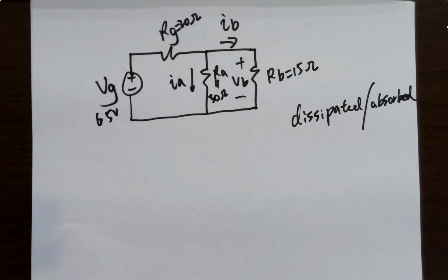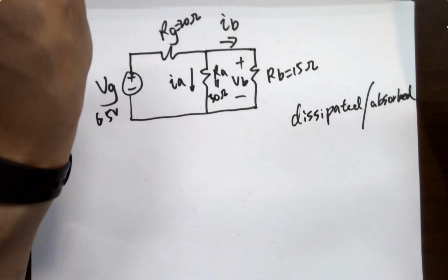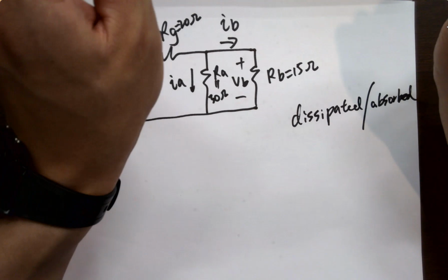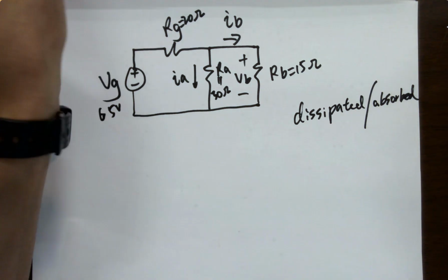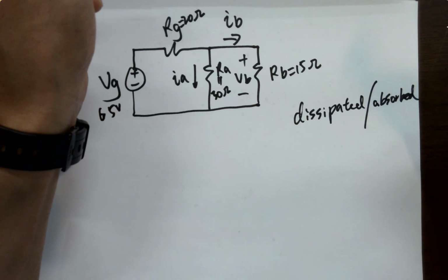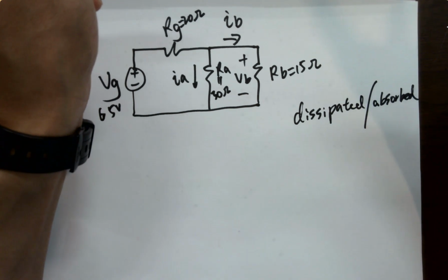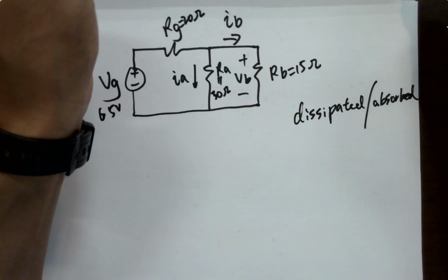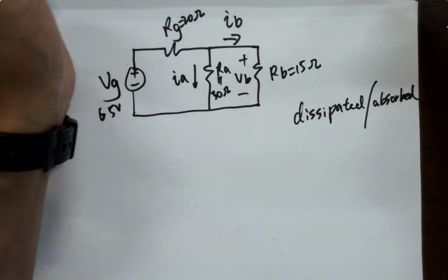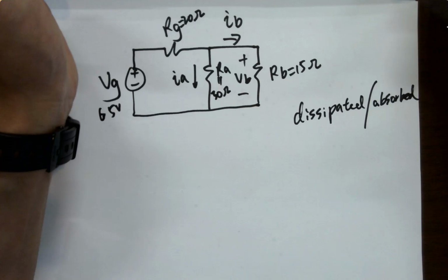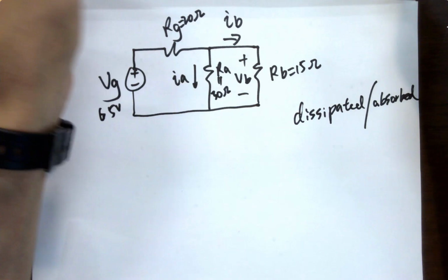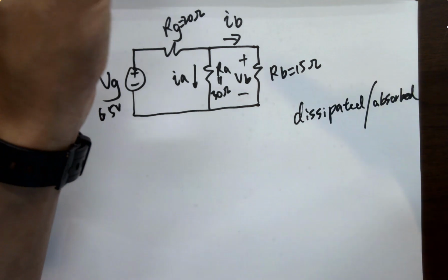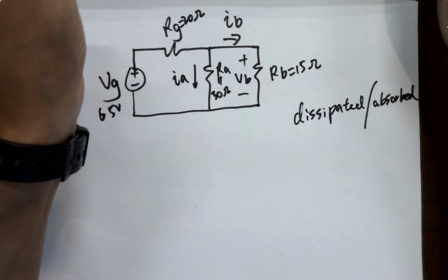So I discovered that the freezer has a heater inside. Can't believe that. The heater is a low resistance resistor, usually 20 ohms. It's just a resistor, just a metal bar. And it heats up to melt the ice building on the back of the freezer. But you are thinking, it's heating up, how do you still get the temperature down to like minus 20 Celsius? It's not affecting it because the heater is just heating locally, just melting the ice, so you're still getting minus 20 Celsius inside.